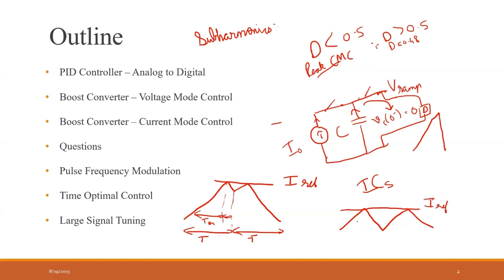In steady state, the on time should settle at a steady state value. But here the on time is oscillating from one value to another different value. So instability means that after every time period T, the inductor is not reaching its initial value. You could say that in that sense.